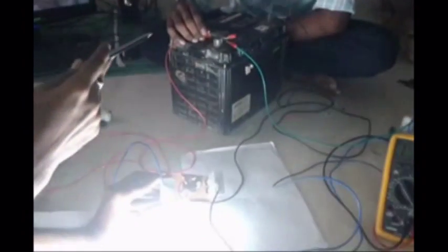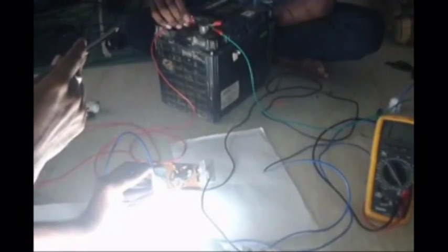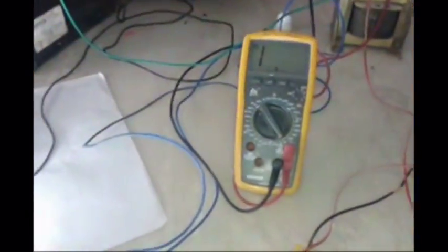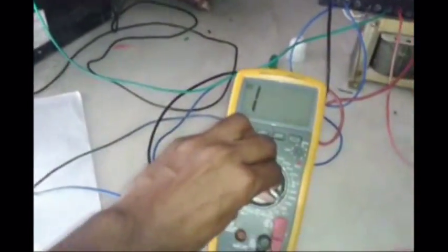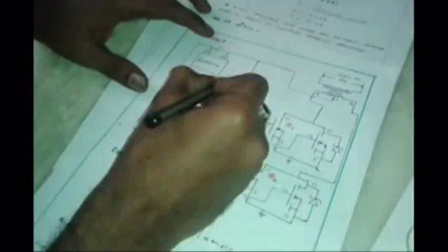You can see that. Remove the battery input. You can see the inverter keeps working for a certain time, because this acts as a reservoir. You can see the bulbs are glowing less. Now they will turn off automatically after a certain time. So we also covered the use of this C1.